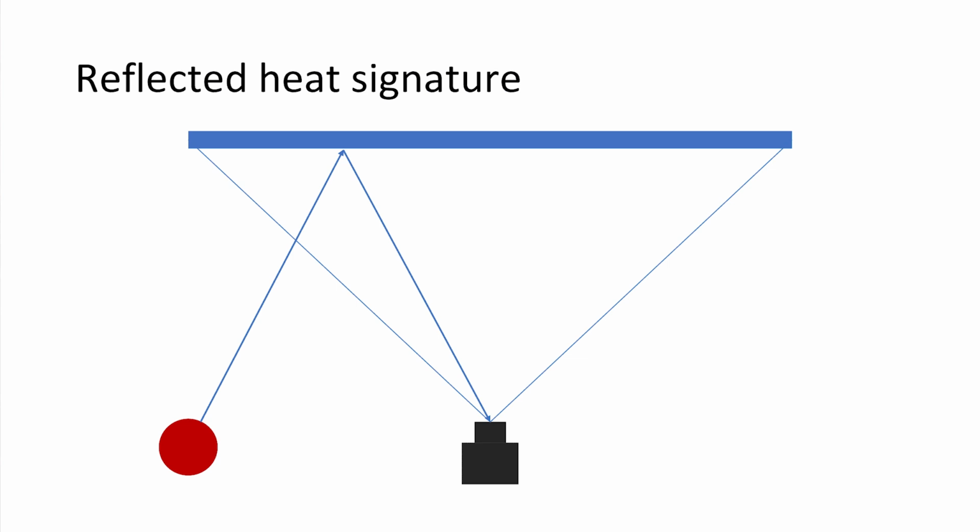Now here's what we're talking about, these reflected heat signatures. So if I have a camera, I'm looking at this area here, and I have a heat source over here, it's going to bounce up and reflect back into that lens. This is going to appear to be a hot spot. This is actually hot, this surface isn't, because we're radiating heat. Remember, this measures heat, so radiant heat will bounce. So think of that like the person standing in front of the glass.